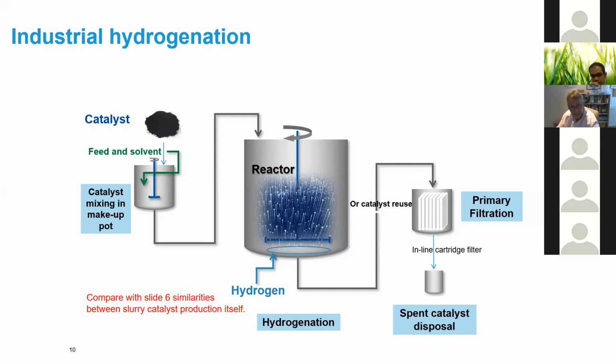Because the FDA doesn't have any idea about what byproducts might be contained or trapped inside the catalyst. So in the more kind of petrochemical, fine chemical applications, that's where catalyst might be reused and sent back for a second, third, or sometimes it can be used 50, and I've seen catalyst used 100 times with a little bit of fresh catalyst added to help.